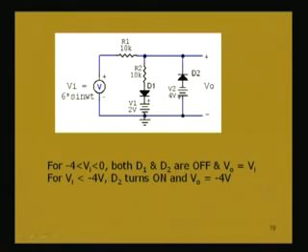So, when this diode D2 turns on, what will be the voltage across these 2 points? As this diode is ideal, there is no drop. So, this voltage is nothing but minus 4 volt. When the diode is turned on, it is like an ideal diode that does not have a drop, so it will simply be this type of circuit at these 2 points.